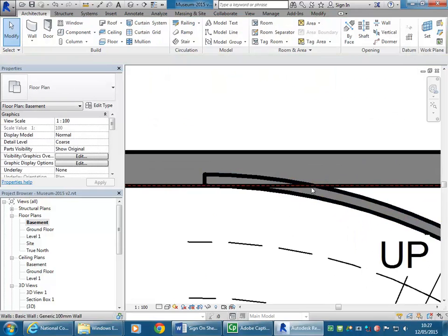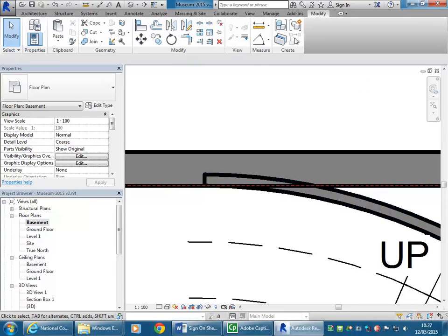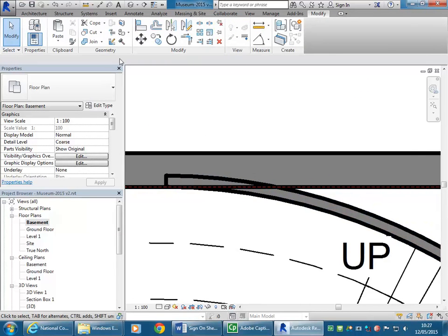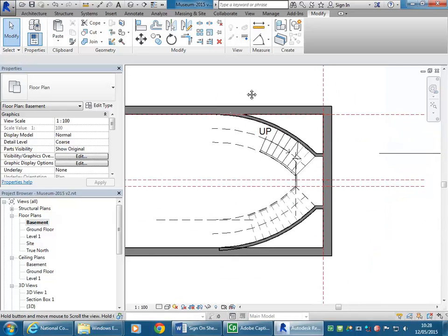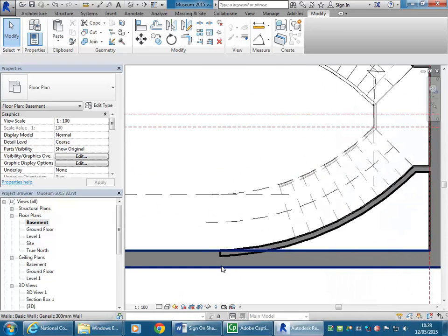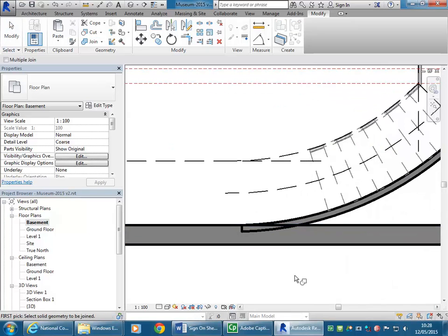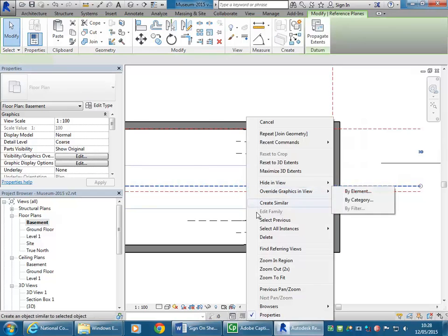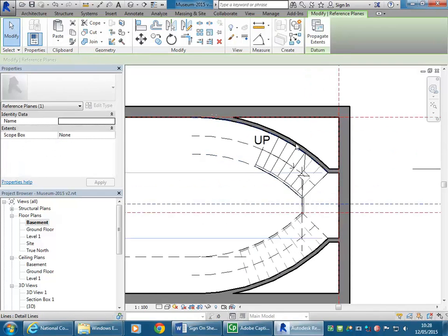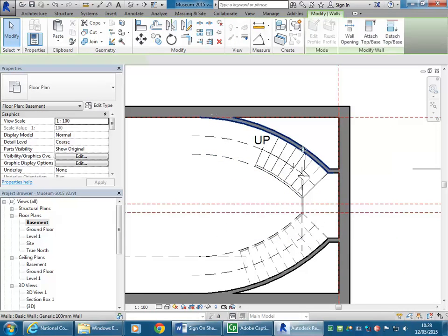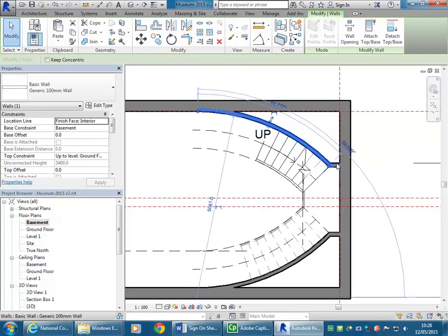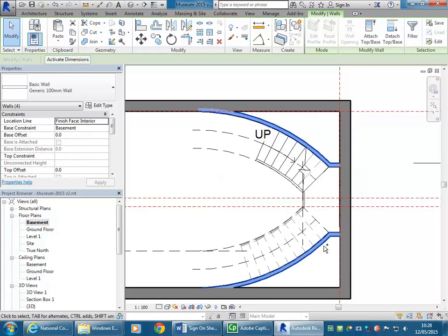Okay, so if you have a situation like this where the walls aren't cleaning up properly, a little tip there, maybe I can just show or remind you about the join tool and use that with these two walls. And the same there, yeah, I'd do that as well actually. So that way, if I need to, I can have more depth for the cantilevering of the walls. It's not a problem to just change that wall thickness to a thicker wall.